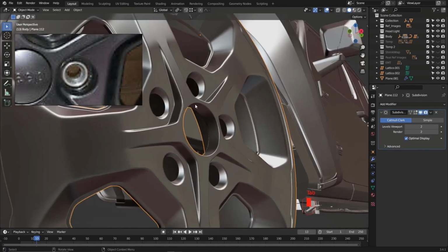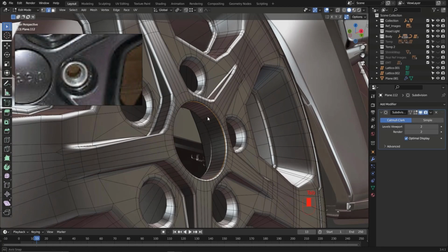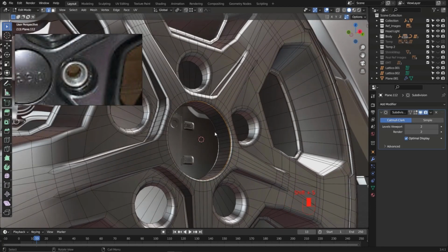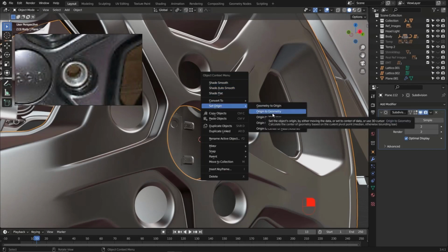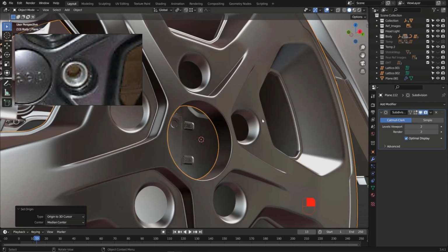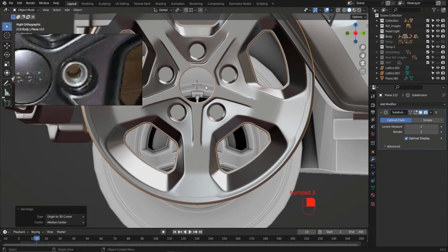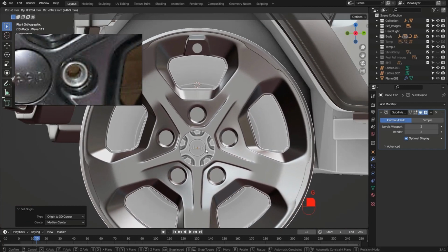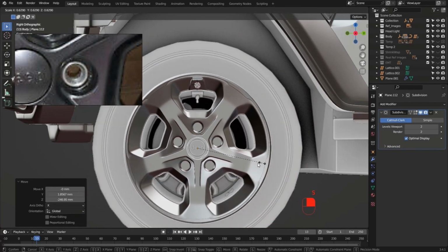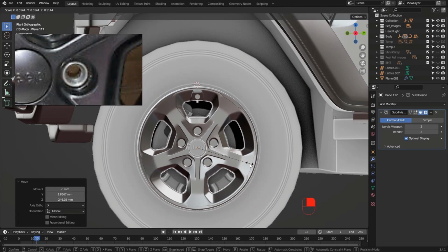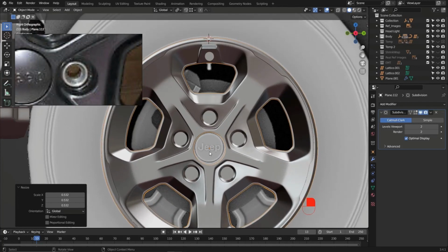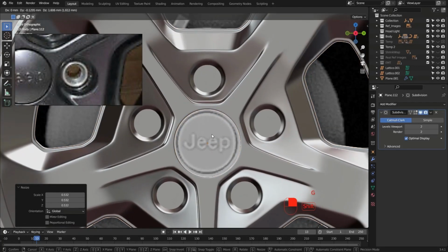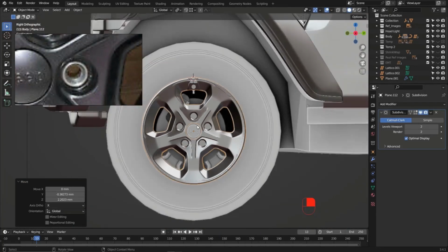You can tab and grab this circle and hit Shift S to bring the 3D cursor right here, and then tab. I just want to move the origin dot to the position of the 3D cursor in the center. So origin to 3D cursor, and now we have it. And G, and let's move this over here. Scale this. Alright, something like that maybe. G, and let's move this a little bit. Try to put it in the center, and now we have this result.